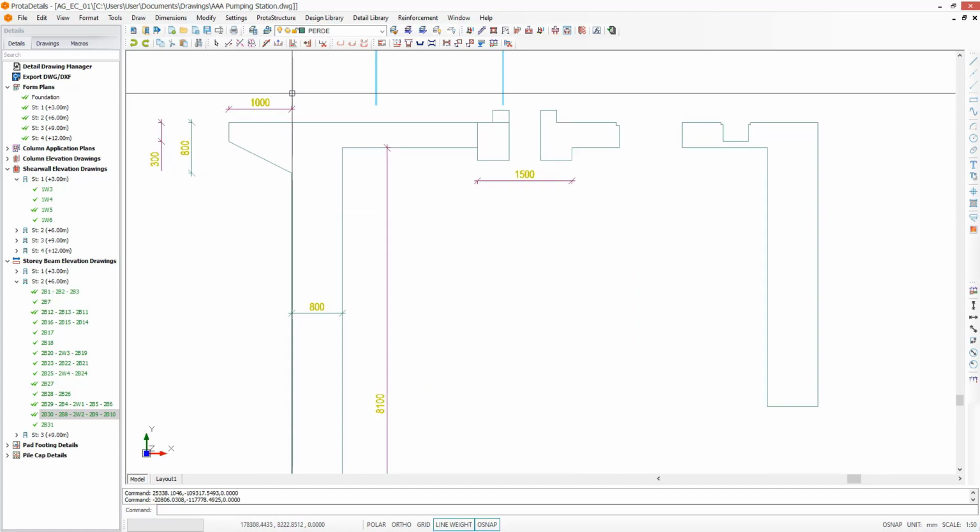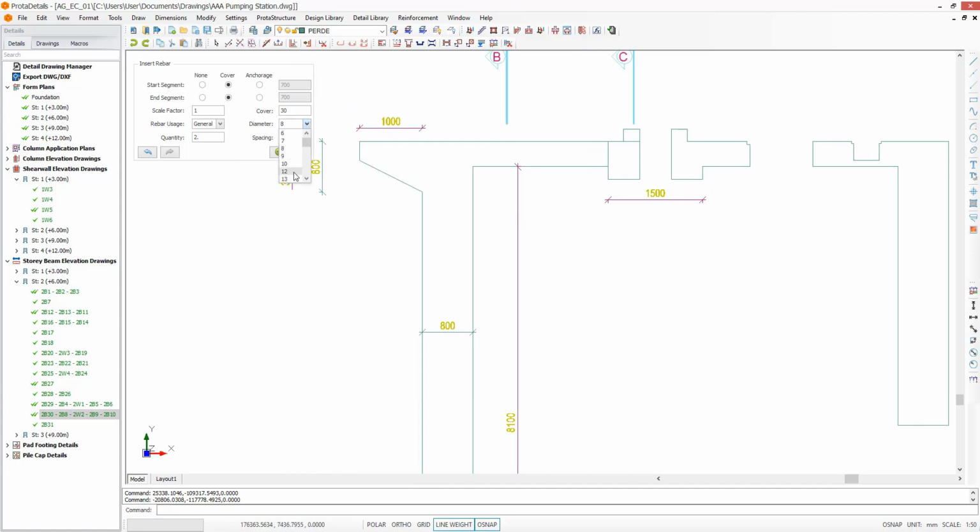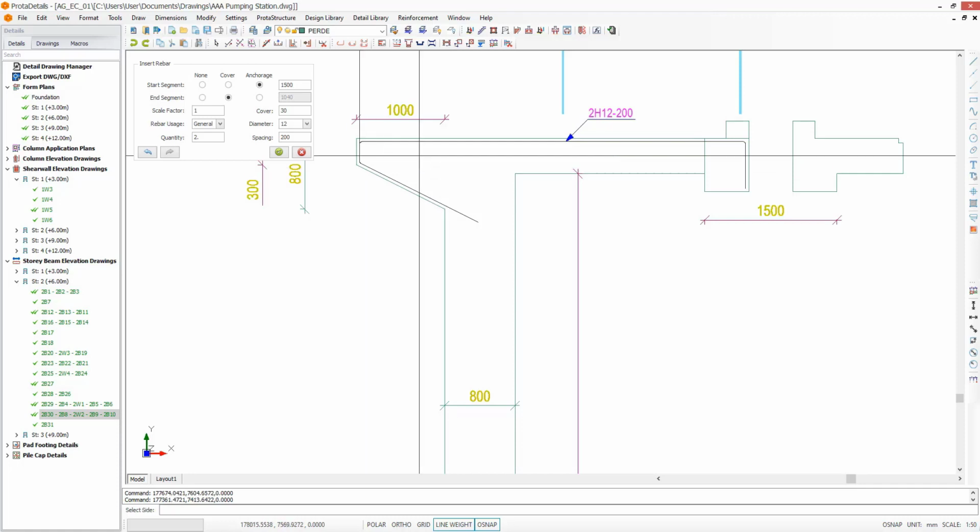with this part now. I will call the insert the formwork command, which is very handy. What I do is I select the diameter first, and the cover, and all the other parameters, of course, and I just simply click around. I select this specific line and show which side the rebar should be positioned, and I continue. At the end, I want to use cover, but in the beginning, I would like to extend beyond the anchorage. And when I'm done, select, and I will do the same for the bottom bar here.